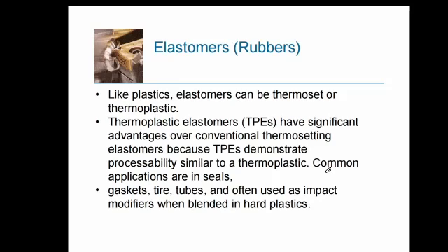So you have elastomers that can behave as thermosets and some that can behave as thermoplastic. So there are some rubbers which you can heat, they become viscous into a liquid. If you cool them, they solidify again like thermoplastics. But there are also rubbers which, if you heat them in repeated cycles, they react and form char.